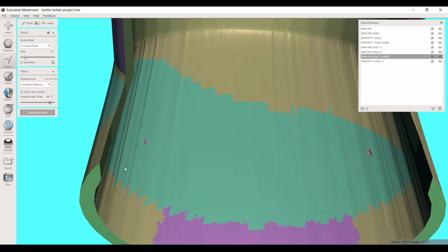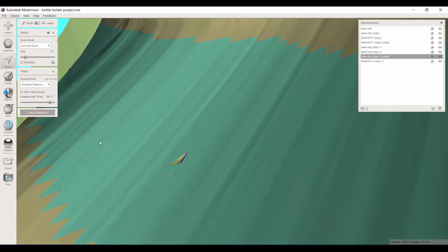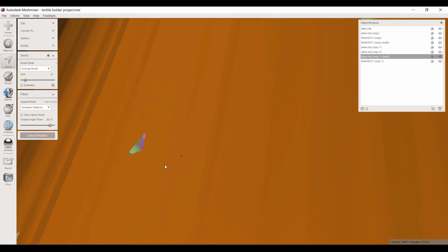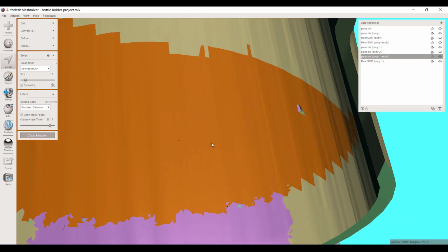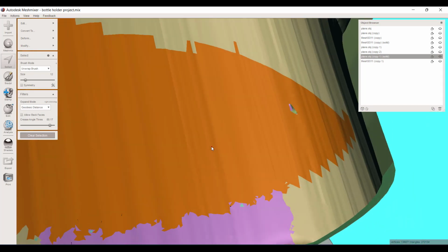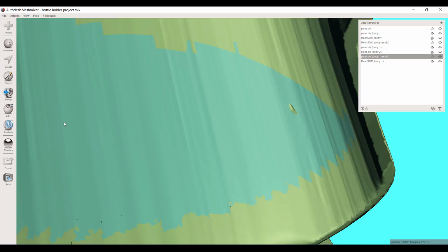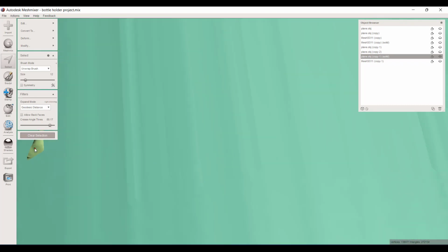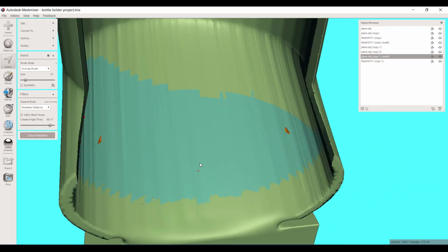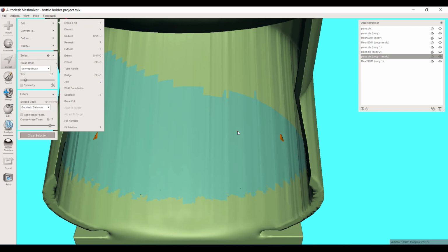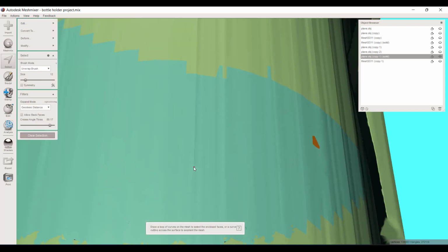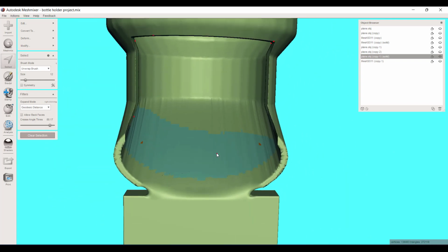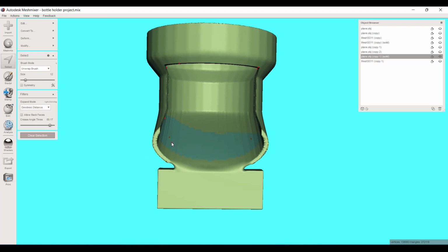Instead, what I could do is whenever you do those Booleans, it's going to create a face group. And so since that's a bunch of different colors, right? I could select this and say invert and create a face group. That's Control G. And now that just lets me double click this, double click that, and now I could go to Edit, Erase and Fill, or hotkey F. It just erases that mesh and does a straight fill in over it. All right. So I like all of this. I don't want to alter anything.